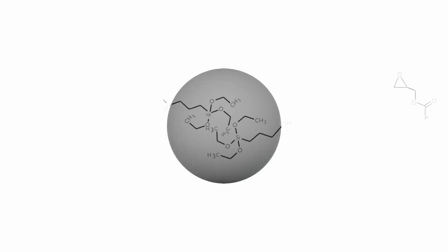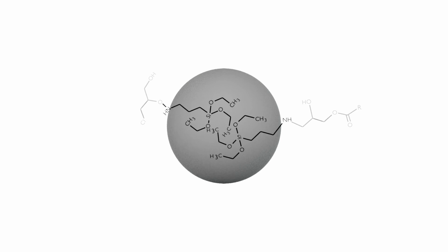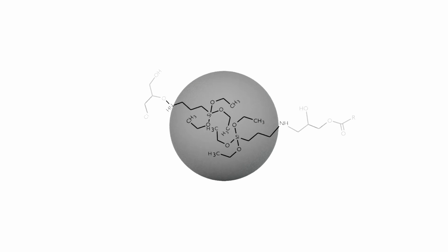During this process, toxic chemicals are separated from the refined palm oil by way of physisorption or chemisorption due to the presence of polar functional groups such as hydroxyl, amino, or carboxyl groups formed on the surface of the functionalized material of the adsorbent. As a result, the toxic chemicals are retained by the functionalized adsorbents, and the treated refined palm oil is directed to a designated collection tank.